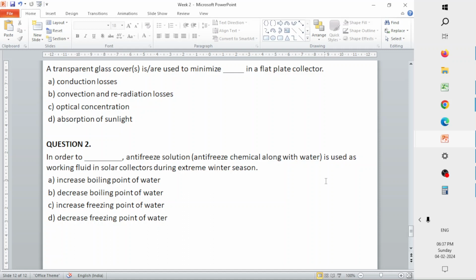Let me first discuss the concept generally. When we discussed the tube, I didn't discuss this part. Water is specifically used for this purpose. The fluid that we use for transferring the heat is water. The reason is, first of all, it's a universal solvent, but that's a general term. The second and most scientific explanation is that it has a high volumetric heat capacity.